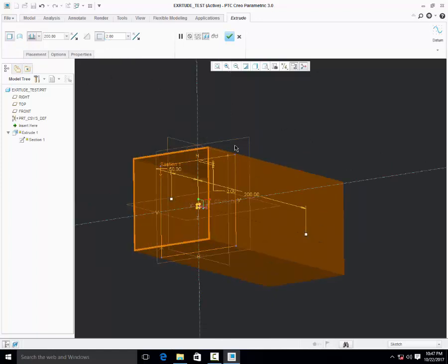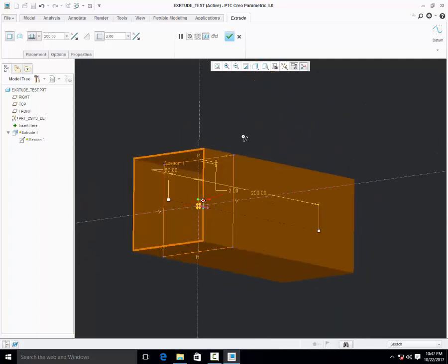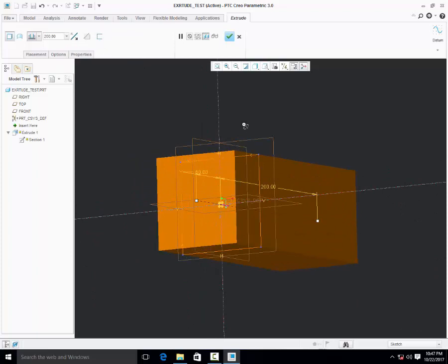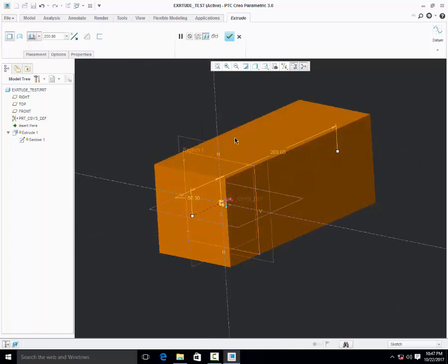In the extrude option we can use all those things, so I'm disabling this option, keeping the solid itself. Apart from this we have one more option: extrude your part or feature as surface geometry. You need to select extrude as a surface. This is the surface symbol in CREO. Just select this one.